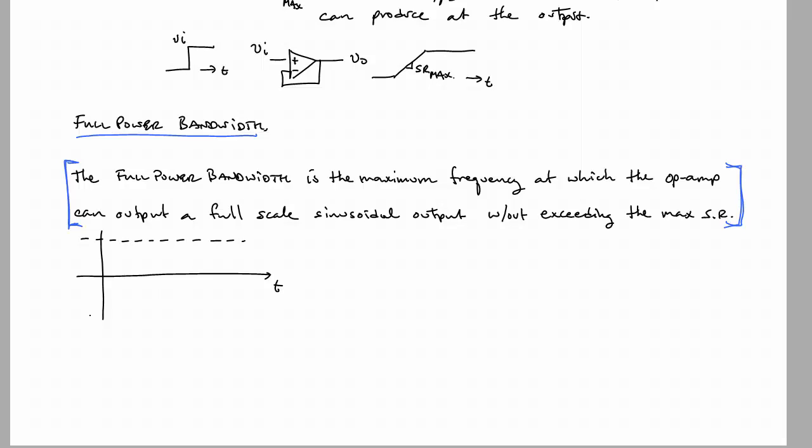and you know that if an op-amp is powered from its power supply rails, and this could be unipolar or bipolar, we're going to assume in this case a bipolar scenario, where we'd call the upper maximum voltage that the op-amp can put out L plus, limit plus, and L minus for the lower one.